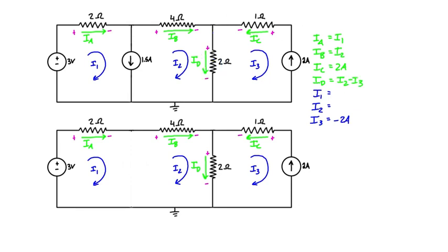And then I1 and I2 are still our unknowns, and that's what we're looking for right now. We do have a relationship to connect them though, even before we go to KVL here, because we know that 1.5 amps is coming down, and we also have I1 going down and I2 going up. So 1.5 amps is the difference of those in the direction of I1. So we just have I1 minus I2 is equal to 1.5.